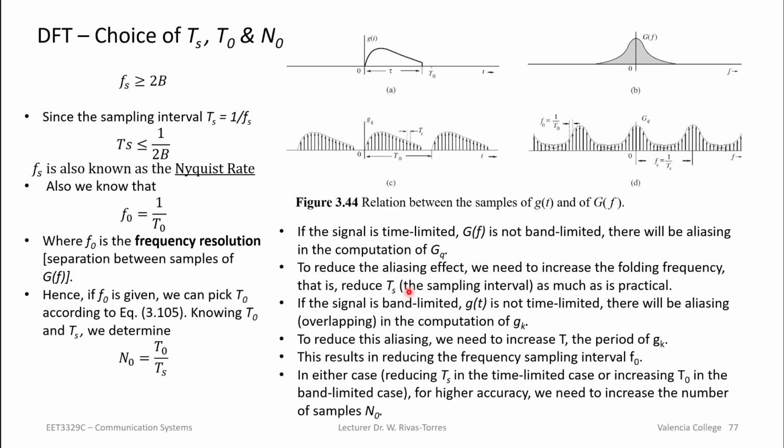Really, the way that we control aliasing is, in every system there's a practical limit to how small you can make your sampling time. So unavoidably, we end up band limiting the signal by filtering it.